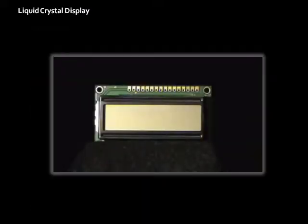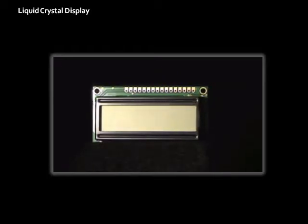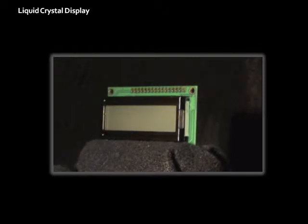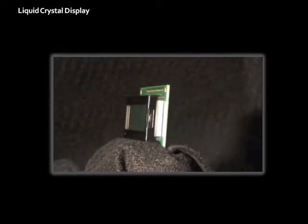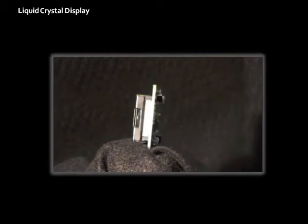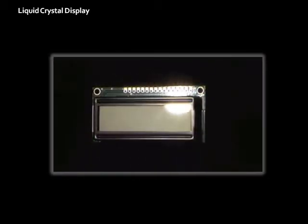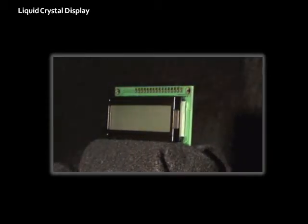LCD displays are used in almost any type of product, from automotive, medical, handheld, industrial, and consumer applications. LCDs require either ambient light to be reflected or a backlight to transmit light. LCDs are most often made as modules with a controller. The built-in controller provides the required voltages to twist the liquid crystal material. The controller receives parallel or serial instructions to display the desired fonts or turn on the selected pixels.